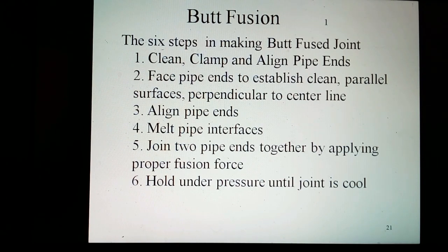Butt fusion of pipe products with different wall thicknesses. Pipes of the same outside diameter but having different specified wall thicknesses may be butt fused to each other under special conditions. Since this represents a special situation, it is subject to limitations. Therefore, the user is advised to consult with the pipe manufacturer to determine if the special procedures can be applied to the pipe components involved in the particular installation in question. If so, a written copy of the applicable assembly recommendations should be obtained.